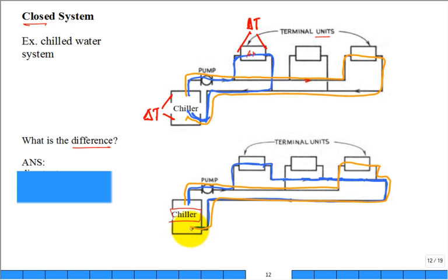So, first of all, if you're a pack of fluid, there's 3 packs of fluid and you want to distribute 1/3 here, 1/3 here, 1/3 there, right? You would like it to be naturally balanced so that the same flow, I'm not changing the sizes of the air handlers. We need 1/3 to go here, 1/3 to go here, 1/3 to go there. Which system, not a clicker question, don't shout it out, I'm going to walk around. The next question now is what system will more easily deliver balanced flow, 1/3, 1/3, 1/3, to those air handler units?